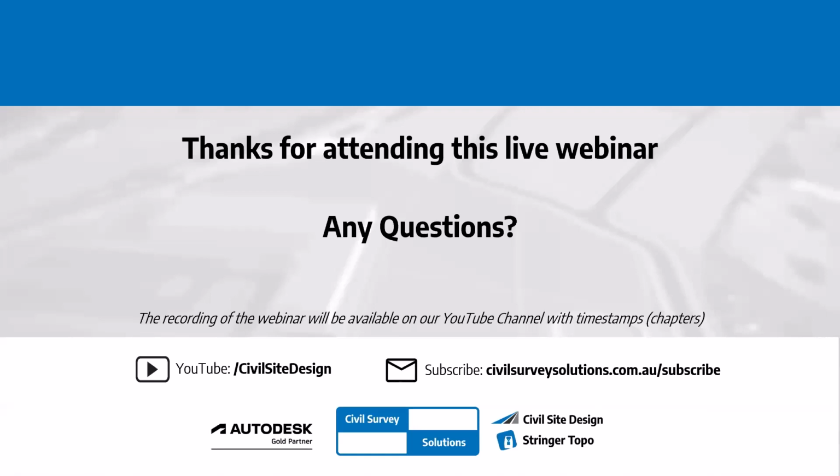Hang on, quick, last question has just popped in. So let's see what that is. Each Cogo Point can have a 3D design placed on a layer. Can they be added to the design surface triangle? I think you answered that anyway. The answer is yes. So you can use the point groups. You can use the point group to filter which points you're interested in based on a code or a number. And then you could make a terrain model from that particular point group. So you could bypass the polyline and the grading altogether if you really wanted to. So the answer to that one is very much yes, just a slightly different process, but Jonathan did show that very quickly about 5 minutes ago.